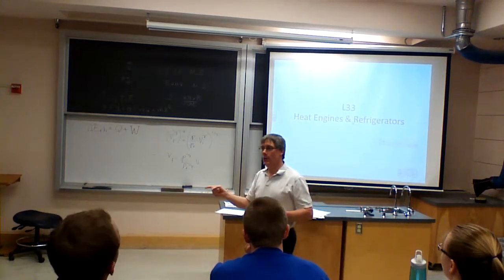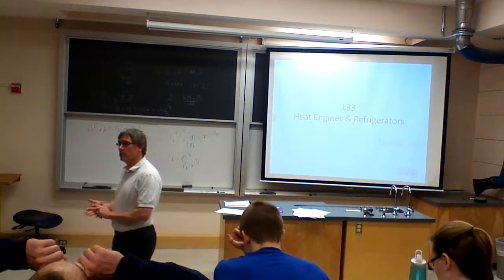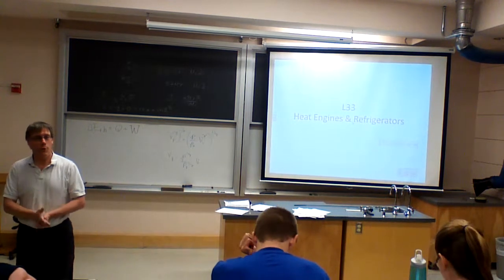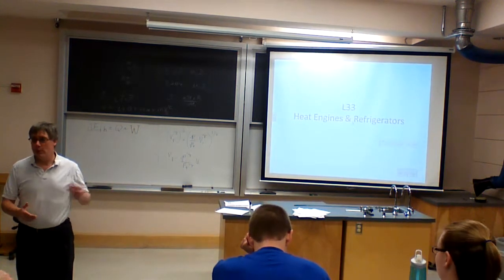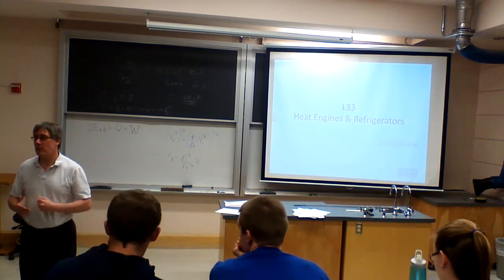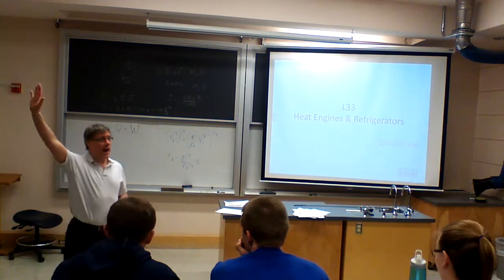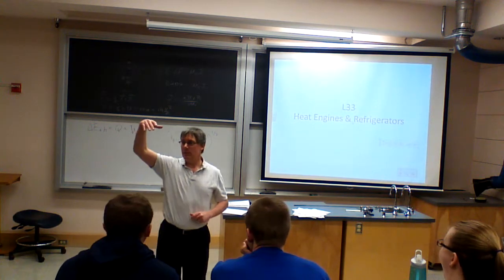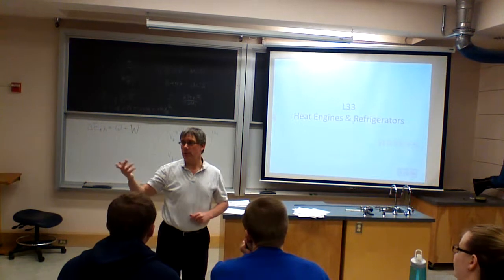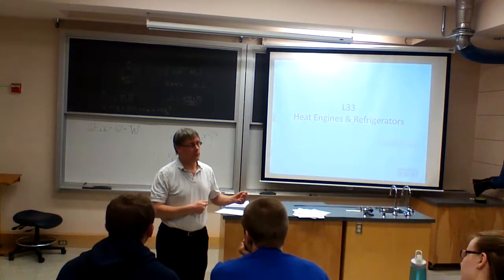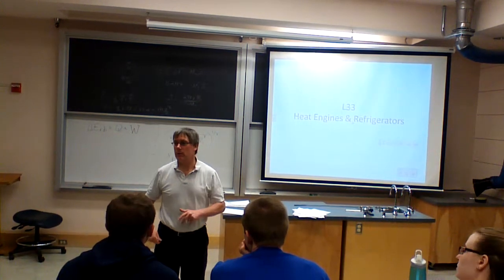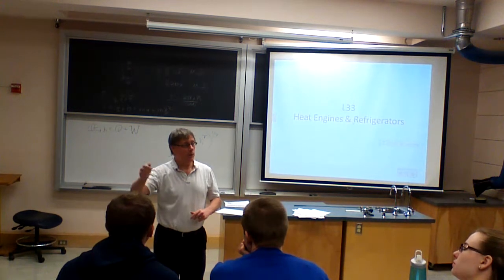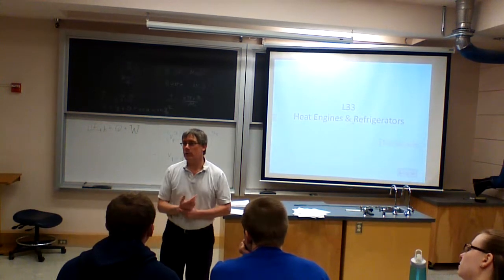I'll tell you where there's heat in the refrigerator. Those are the two places there's coils. There are coils inside that are colder than the refrigerator, so heat goes from the inside to those coils. And then there's coils in the back. They get really dusty. By the way, if you want to pay Avista or your local utility less money, every once in a while pull your refrigerator out, find all the weird stuff underneath it, clean it out, and dust off the coils in the back, and then your refrigerator will be a little more efficient.